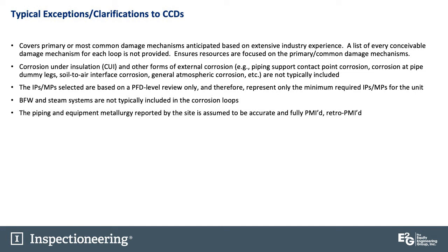So you want a good handle prior to doing a CCD. You certainly want a good handle on knowing the metallurgy, accurately knowing the metallurgy in your plant. It'll be hard for an SME to identify key risk areas if he does not have the full story on what the metallurgy is in the unit.